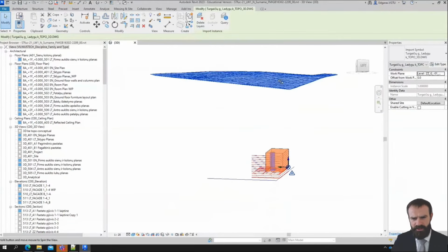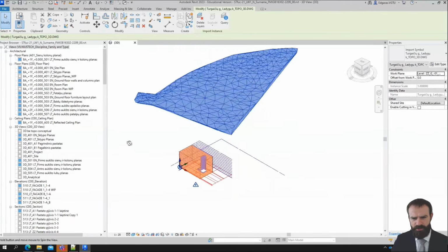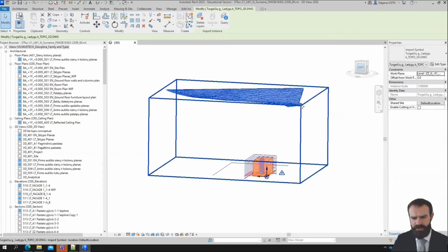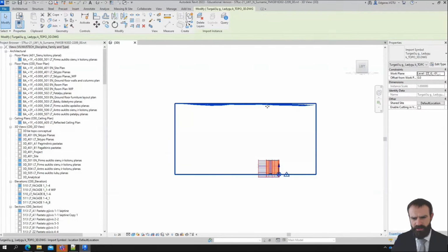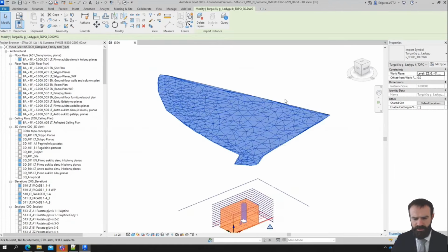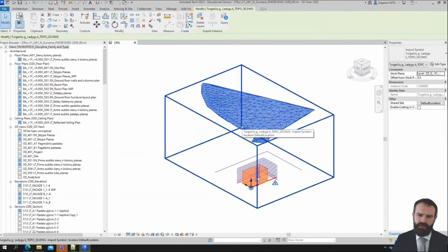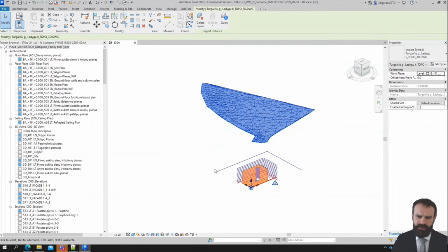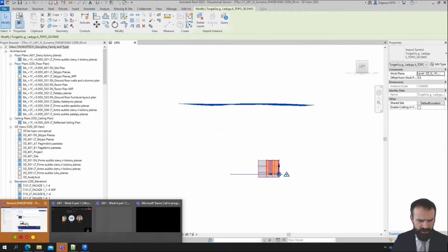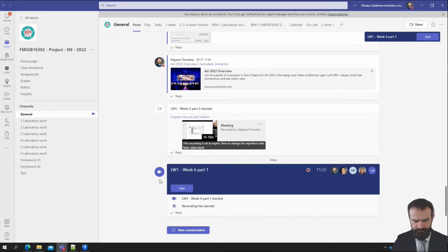So I have the 3D surface of my project, and now you can see this project is hanging in the sky, because when the program imports AutoCAD, the base layer is used like the 0 layer, so it means I need to move all this top surface down. How much I need to move it down, it depends.